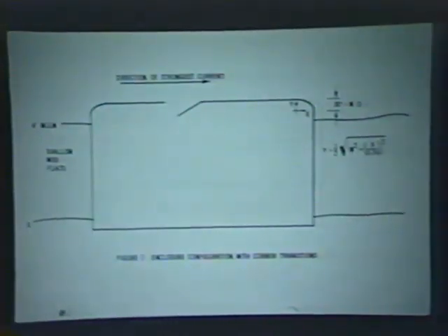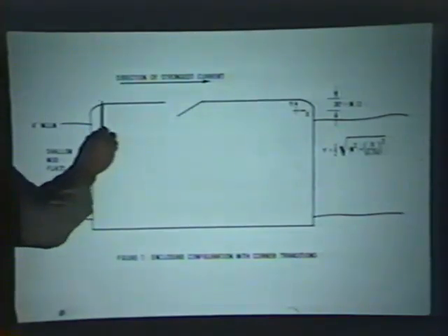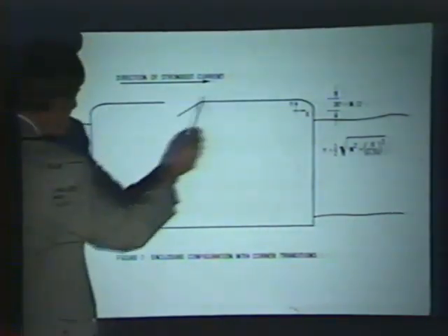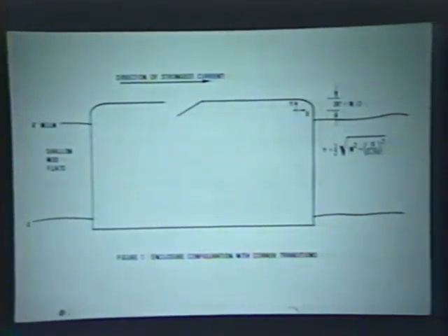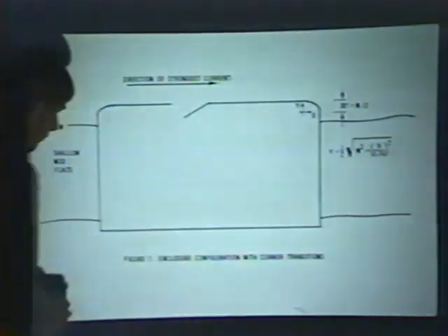And it has the features that I described earlier. The rounded corners tend to keep this wall clear. If you don't do that, then a fillet fills in alongside the wall. This is the bottom. A fillet will fill in like this along the bottom edge of the wall. And by using these corners, you can reduce the fillet there, and particularly right in front here. The direction of strongest current was this way, so we put in a baffle to prevent circulations of this sort inside of the harbor, which you get without that baffle.